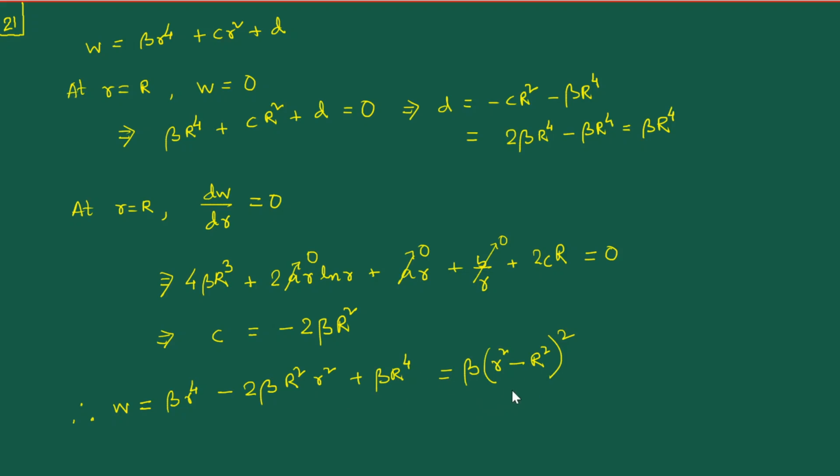All right, so this is our solution, and if you just wish to write this, this is q by d, and so this comes with a 64. Let's not forget that. So this is our solution. Nice clean solution, and as expected, this takes on a very nice axisymmetric form also, and you can actually check that the W is going to be maximum at r equal to 0.